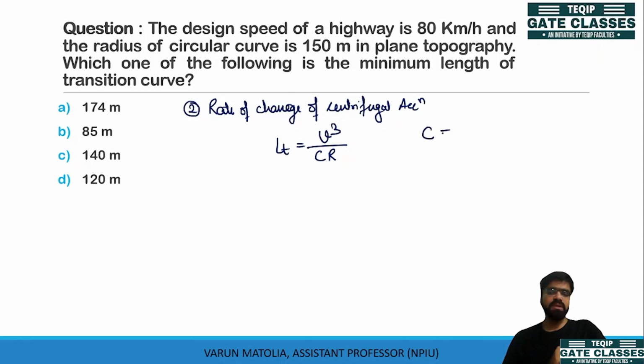Here the C value is 80 divided by (75 plus V in KMPH). Let us calculate the value of C. Generally, it comes out in between 0.5 to 0.6, as we have already studied. But for this question, as we have the velocity, we can calculate it.